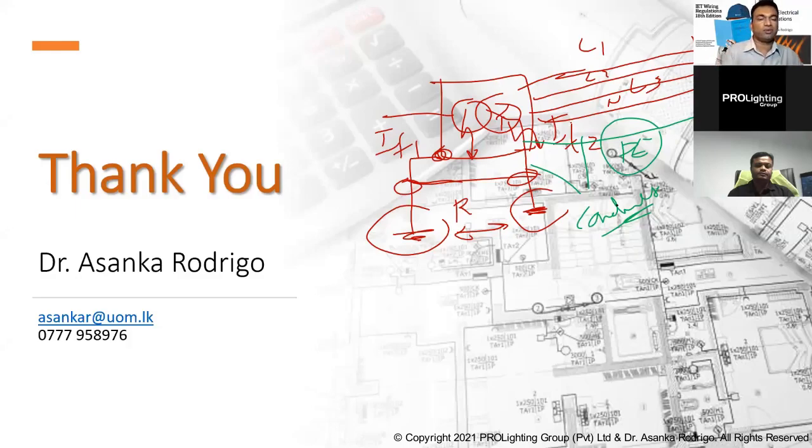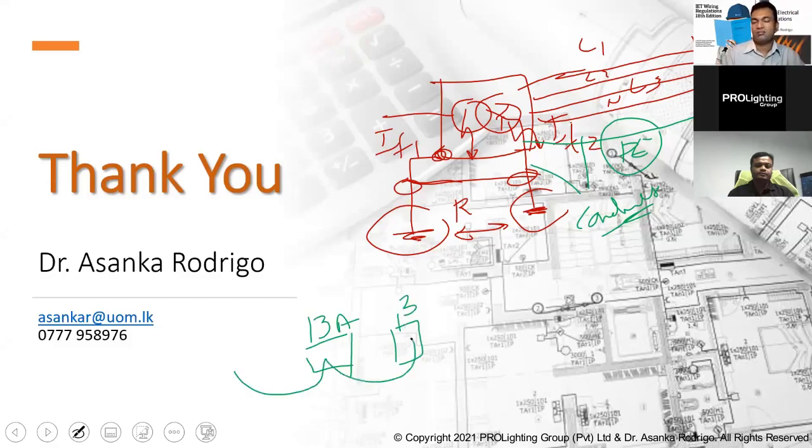Because if you have a number of socket outlets, the problem is that this is 13 ampere and this is 13 ampere, let's say like that. And if you are wiring them using the overcurrent protective device, you can see that if you add them, the maximum demand will be 26 ampere. So probably 1.5 millimeters squared with the derating factors will not be sufficient. But for example, if you have one